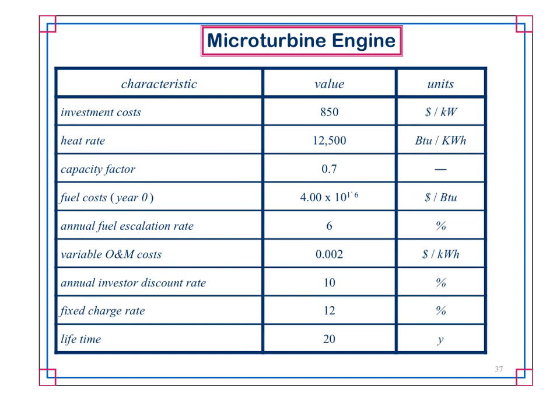But let's look at a microturbine. It costs about $850 per kilowatt of nameplate to buy a microturbine. Your heat rate, if you recall, is essentially a way of saying efficiency. This is a simple cycle setup, right? So a heat rate of 12,500 is pretty good, but not great. It runs about 70% of the time at full output, right?